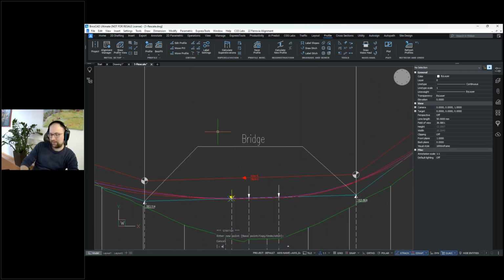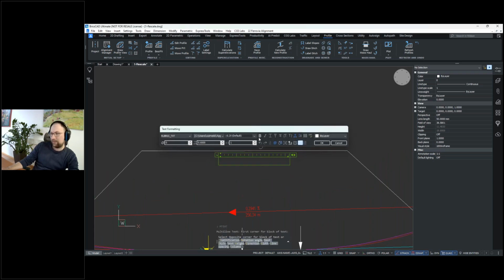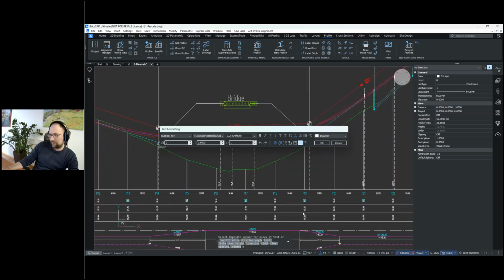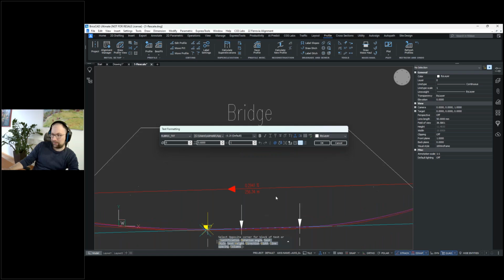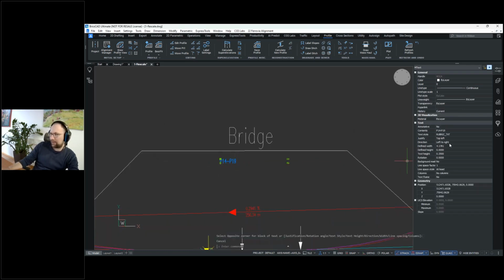And then also maybe we can use multi-line text, so M text. And let's say here we go from the P14 sample line or cross section to P19. And I will just move this justification to the maybe top center here and make it a bit bigger. Okay.